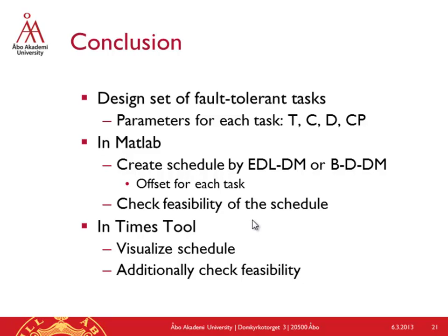You can define rates, I mean periods or frequencies of these rates, and you can define offsets of these rates. The only one thing you cannot do there is to define your own priority arrangement. And the priority arrangement will be the next presentation. I mean priority arrangement in Simulink, how it might be implemented.